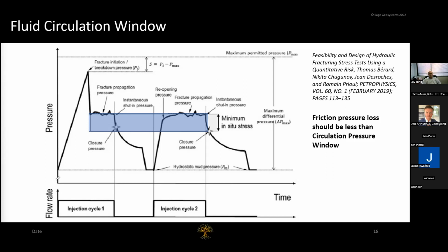Actually, if you look at the details of what was done at Fenton Hill, they understood it. The problem was that to achieve this, you need to apply high back pressure. And applying high back pressure requires power, and this is parasitic load. As a result, as I said, the net power becomes negligible. So it all works, except you cannot generate a positive outcome.